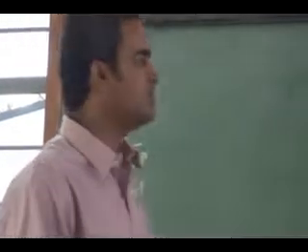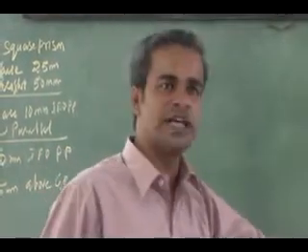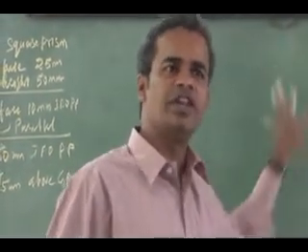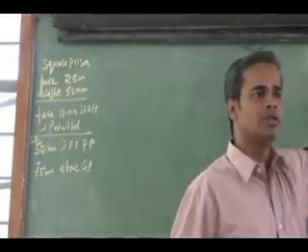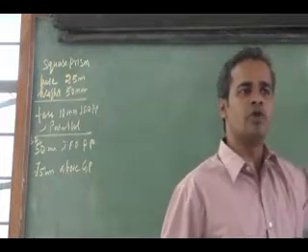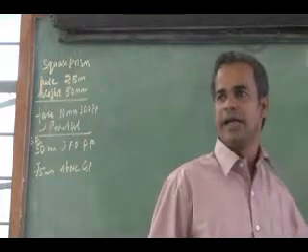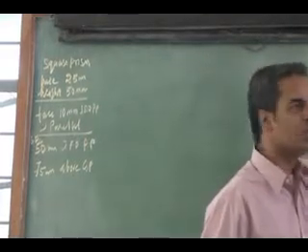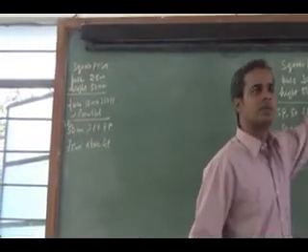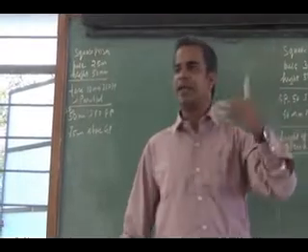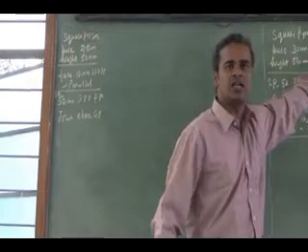So how do I draw it? Station point, where do I have to mark it? To the right side, similar to the second problem. So all the details are given. Only this square prism will be seen in the top view, and a rectangle for the height will be seen in the front view. While drawing the square, 10 mm will be in front of the picture plane, so you have to draw the square at 10 mm in front of the picture plane. And the face is parallel. Similar condition, I have to draw it.